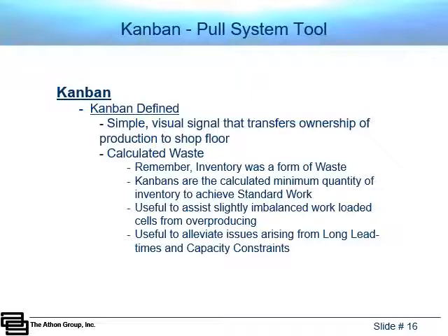The waste of carrying that inventory is much less than the waste of having a piece of equipment run dry because it has nothing to work on, or starving a customer for what they want, or having long lead time because we've got so much WIP in process. So Kanban, yes, is a calculated waste, but typically in my experience when I've implemented Kanban, we've actually driven inventories down, contrary to what you would think when you think about a Kanban system.